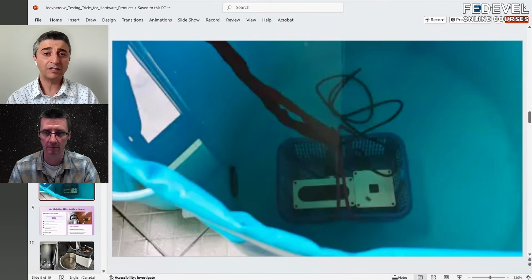The other thing is, sometimes it's not dust, sometimes it's accessing the port. So there are devices where it's not IP60, it's IP54. So it's not about fine dust particles, but you don't want a finger to cross an opening of your device because it's hazardous, because it's high voltage, for example. So you want to make sure that yes, water might get in, but I don't want people to put their fingers in and get shocked. So this is where you go to IP54, for example. Yes, dust is important, but sometimes other applications require that you don't have easy access, to avoid blocking the sensor or for safety reasons.